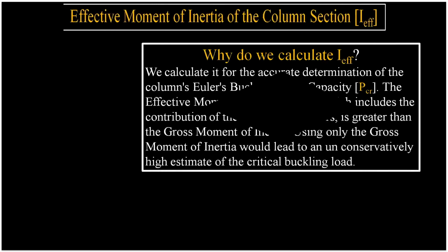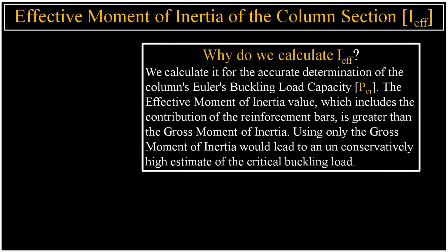Title of this slide is Effective Moment of Inertia of the Column Section, IEFF. We will now calculate the effective moment of inertia along both the XX and ZZ axes. Why do we calculate IEFF? We calculate it for the accurate determination of the column's Euler's buckling load capacity, PCR.